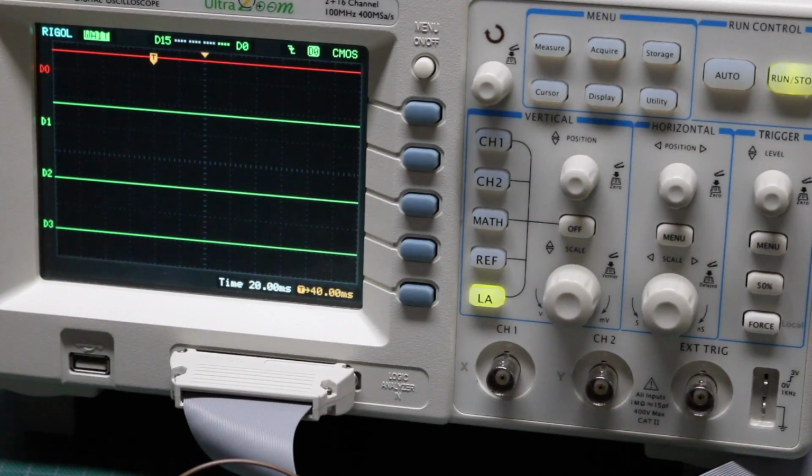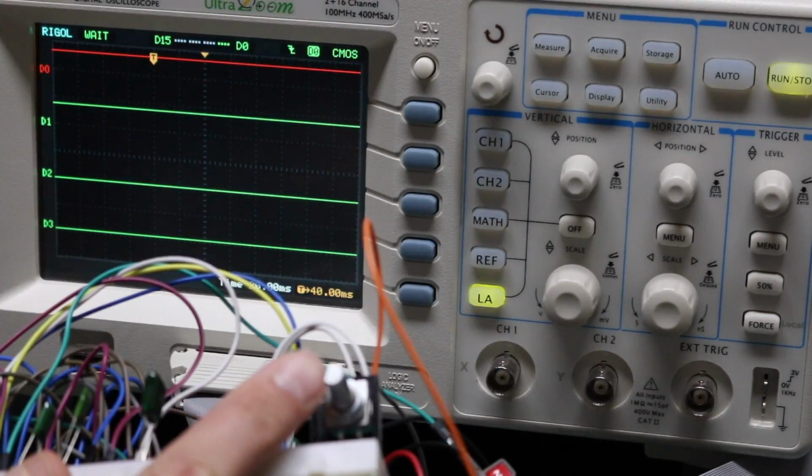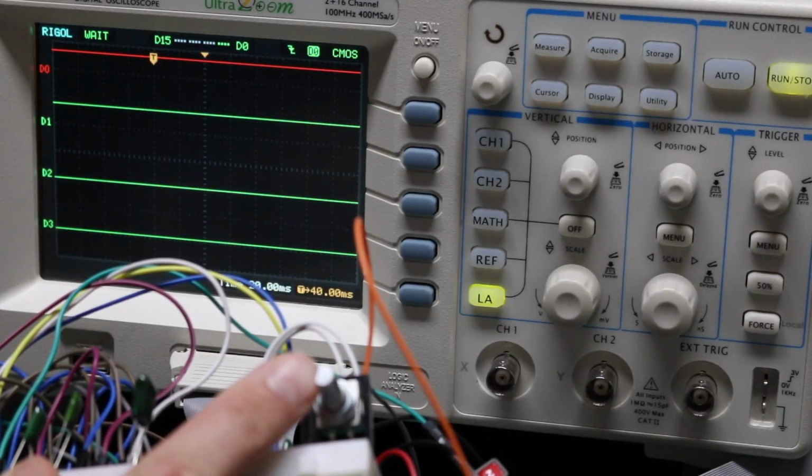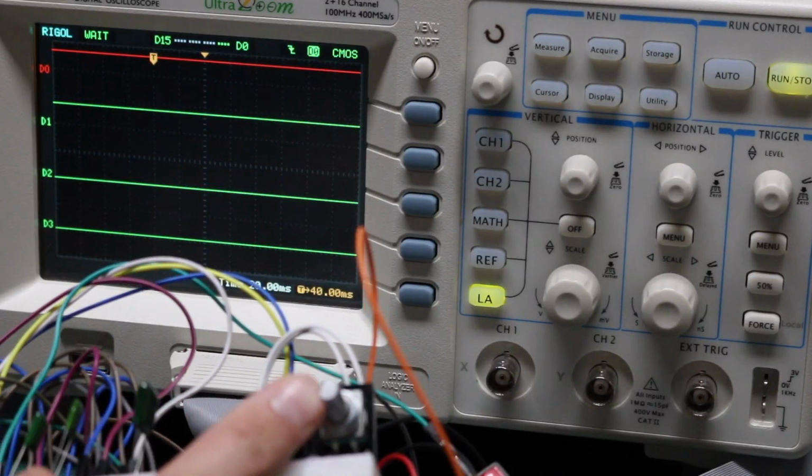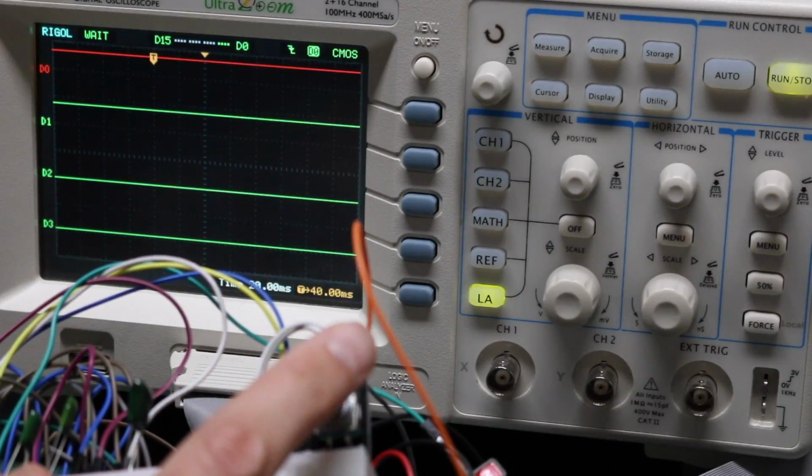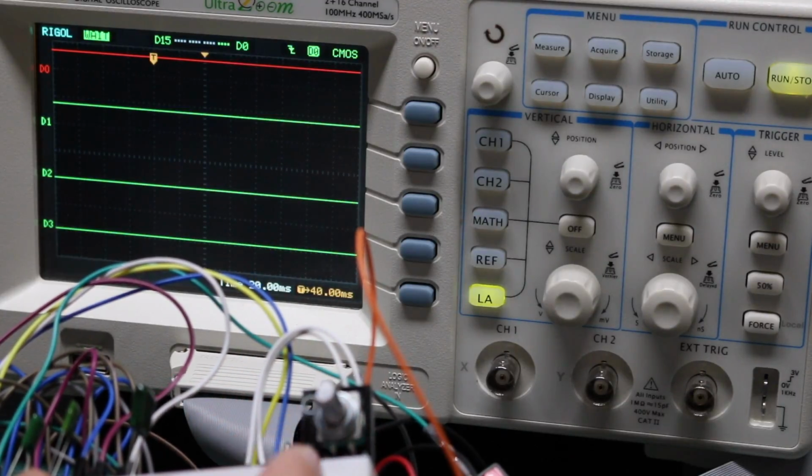So on the logic analyzer, D0 is rotary encoder signal A, then we have signal B, so those are going into the logic circuit, and then coming out we have my generated clockwise signal and my generated counterclockwise signal. So the flat edge of the encoder knob is over here on the left. I'm going to rotate clockwise several times and just see what happens.